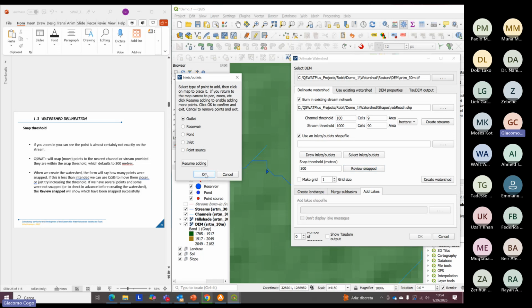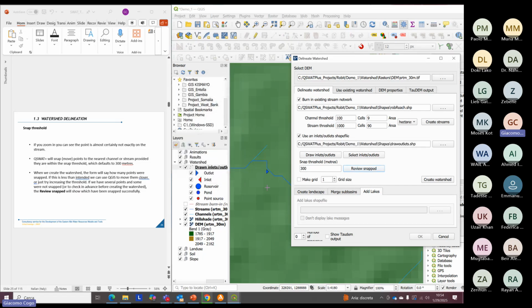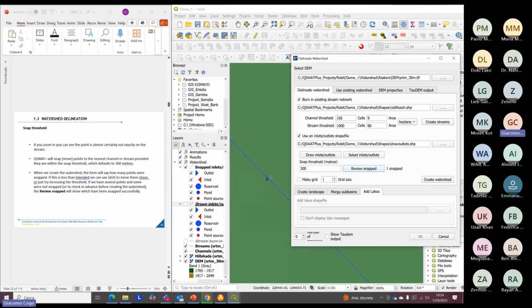So you have to press OK here. Now we can click on this review snapped, you see it writes here one snapped, so it found this outlet that we have created, and it has been moved, if we zoom on the map, exactly onto the channel, on the streams that we had created before.